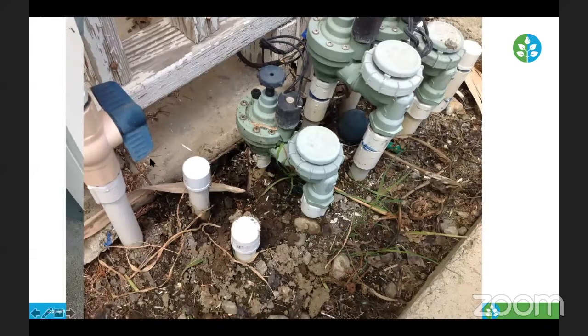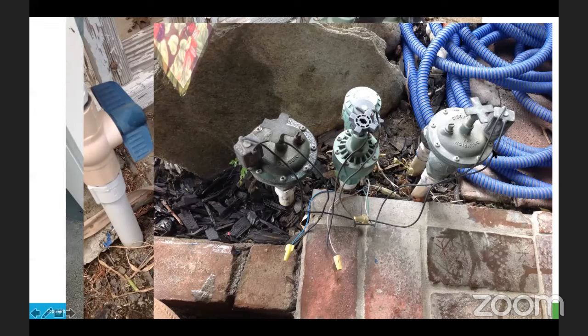Right, so here would be the isolation shutoff valve, where they would be able to shut that off and then have the water off in the whole entire system. Here was a replacement valve. So this was a newer valve. These are brass adapters. They still are anti-siphon because the body has the anti-siphon. In my opinion, it's always best to replace like for like, meaning if you need to replace a valve, you replace it with what was already existing, just to have continuity and to have everything be uniform.